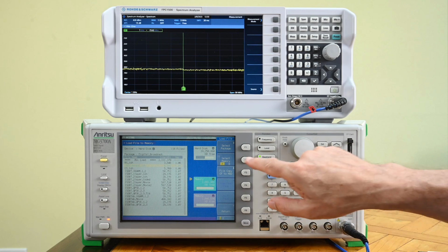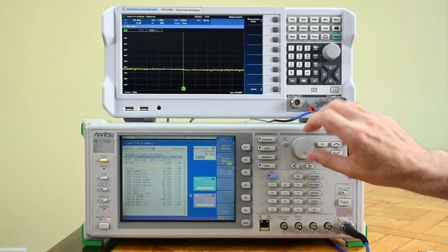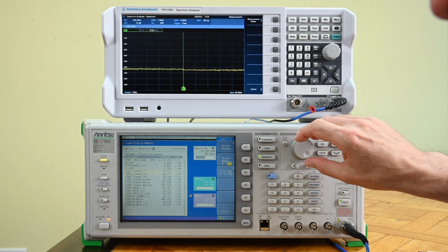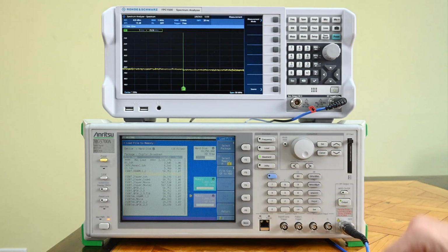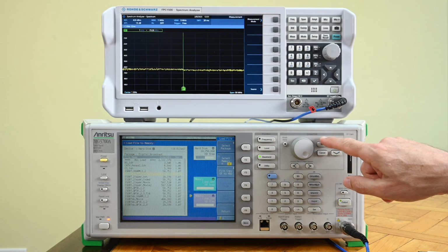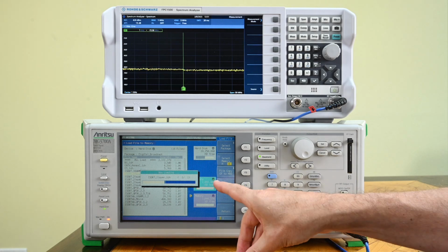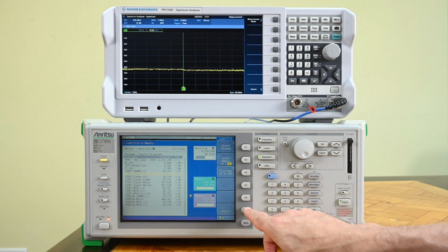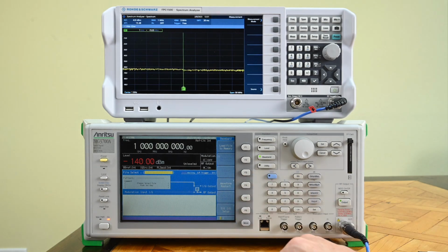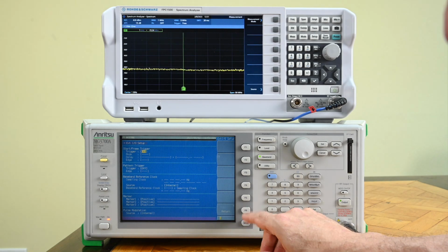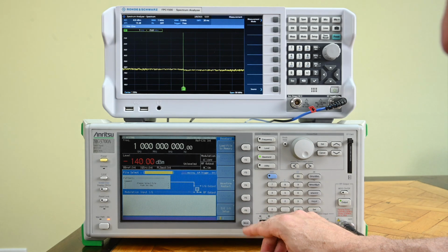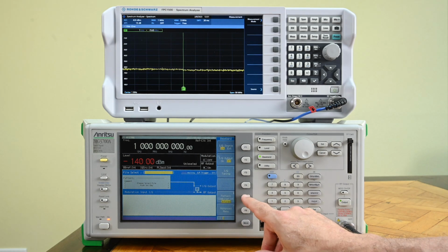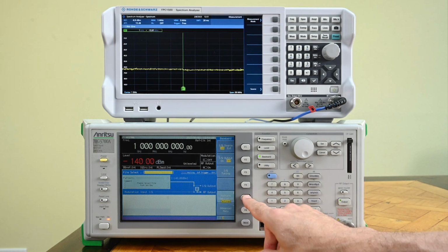So I'm going to choose that one, and load it into waveform memory A. And for waveform memory B, I'm going to select another signal. Let's just take one of the Japanese digital television signals. So both of my memories A and B now have a signal ready. Now, returning to the main screen, how do I get to play 2 things at the same time? It's by, oh excuse me, that's the wrong button. It's by going to the pattern combination mode.